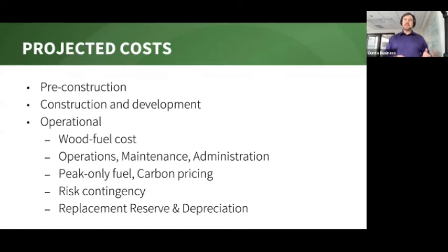So what I've seen in a lot of these old systems is that, let's say the anticipated district heating peak consumption is 200 kilowatts. And then they'll build a 400 kilowatt system. Or let's just say they build that 200 kilowatt system. They build it for peak. We don't ever recommend building for your peak. We say build for a little bit below your peak.